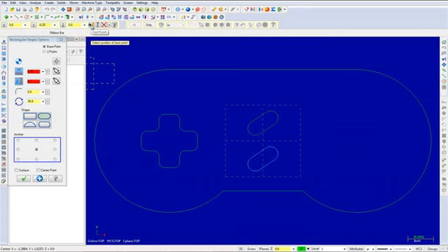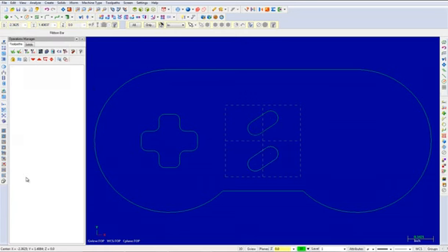You can now select the OK button to exit the Rectangular Shape Options command. Your part will appear as shown up to this point. The next thing that we will do is create circle center points. In this step, you will create the 4 1/4-inch diameter holes knowing the diameter and the center points.